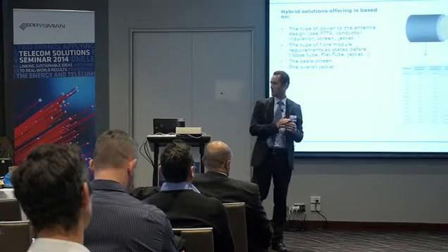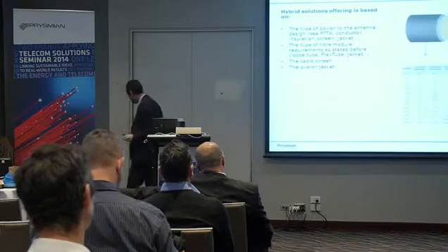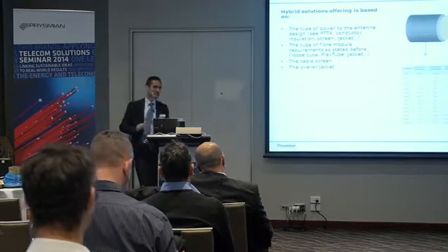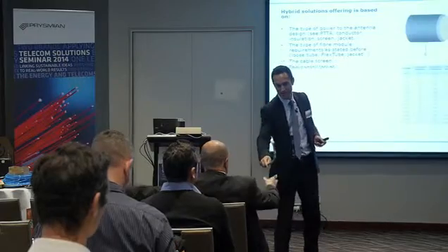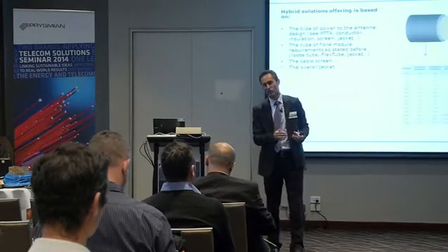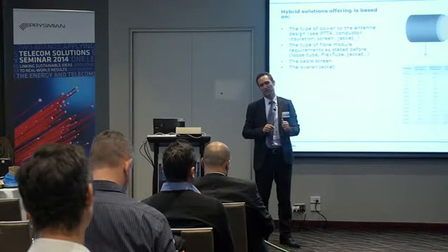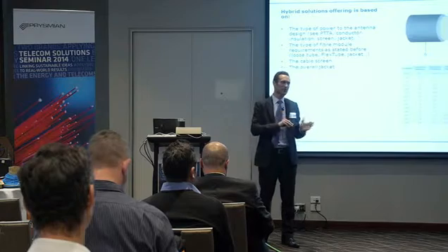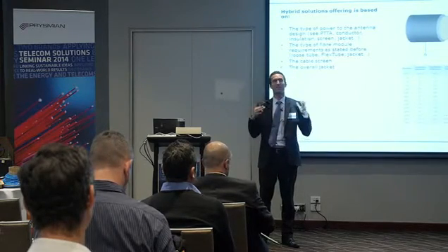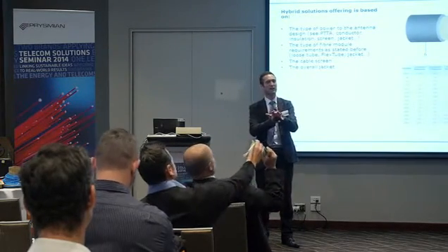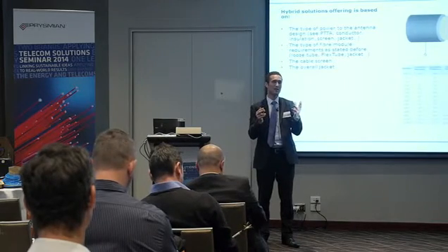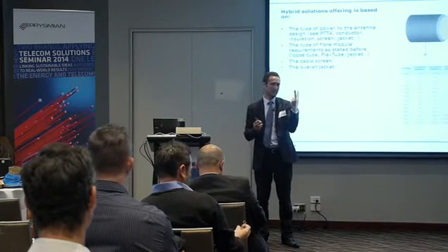In Europe, it really depends. I have a cable here. Maybe because this is Europe, this is not the same size, but it is hybrid also. You have a much smaller conductor and some optical fibers. This cable has been used in Italy. In some other countries, they are not really keen, at this moment, on moving towards hybrid cable, just because the installation crews need to have double expertise, optical expertise and electrical habilitation, to manipulate hybrid cables.